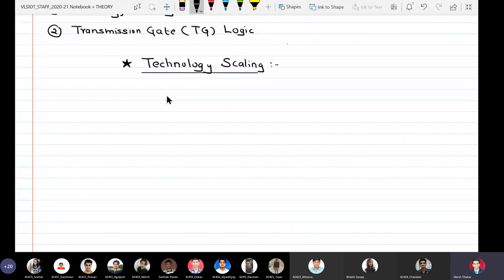So we do not speak about BJT at all, because the BJT device is actually a misfit in the field of VLSI. Only in critical applications where a BJT will surely outperform a MOSFET, we are going to use BJTs, and that too in a very rare logic family called the BiCMOS logic family. BiCMOS is a specialized logic family which combines the merits of both the bipolar family and the CMOS family. Otherwise not.